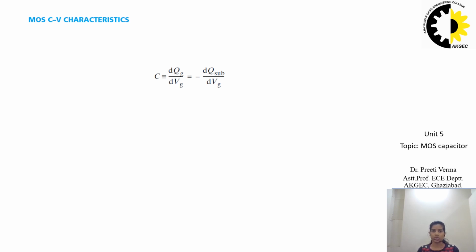The capacitance voltage curve is usually measured with a CV meter, which applies a DC bias voltage, that is the gate voltage Vg, and a small sinusoidal signal of around 1 kHz to 10 MHz frequency to the MOS capacitor, and measures the capacitive current with an AC ammeter.